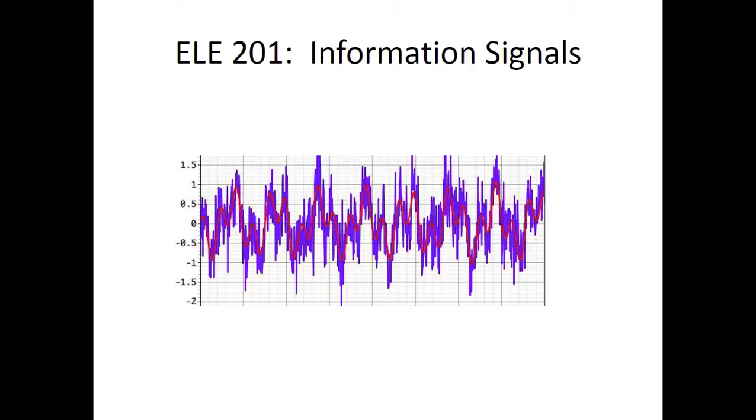Because it turns out you get different effects depending on how you do the average. If you just do an average, if you take some window of points around, so what we mean here is, to reproduce the smooth signal at any given arbitrary point, you take a fixed number of points before and after. Let's say 5 points before, 5 points after. And that's your new output for the signal at that point, right? This is a moving average.